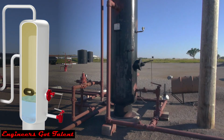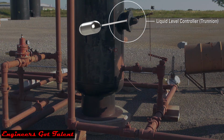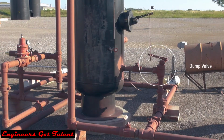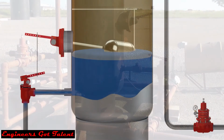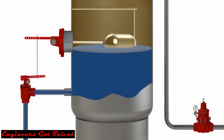The fluid that drops back into the bottom of the two-phase vertical separator is controlled by a liquid level controller, in this case a float ball connected by a mechanical linkage to a dump valve. As the fluid rises, it lifts the float ball in the vessel, pushing down on the mechanical linkage, which then in turn opens the mechanical dump valve.